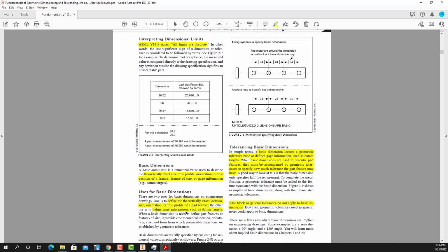Let's say I have to sit this upright like this and measure from something. I might have to have 3 pins to hold that steady. Where these pins are located would be located by basic dimensions, with the size. So this is datum A, datum A1, A2, and A3. This is a datum to hold it in one direction. So we'll look at datum targets.